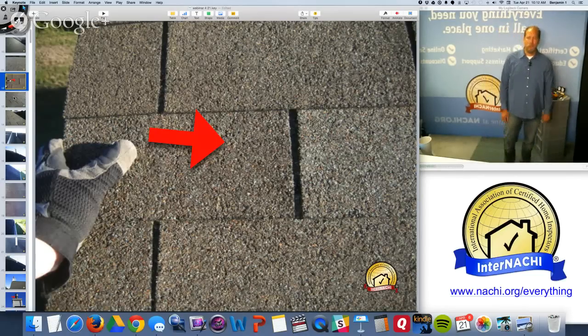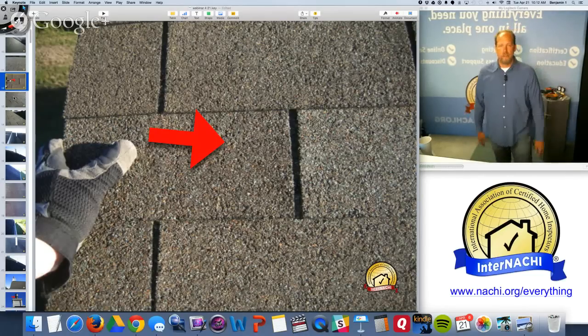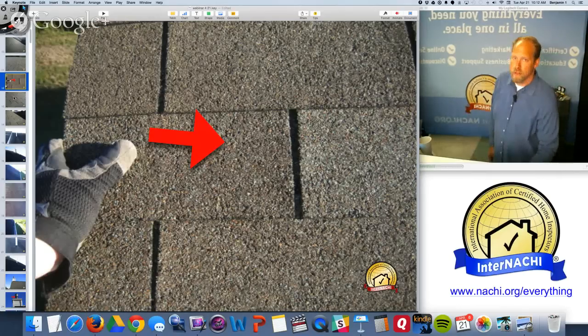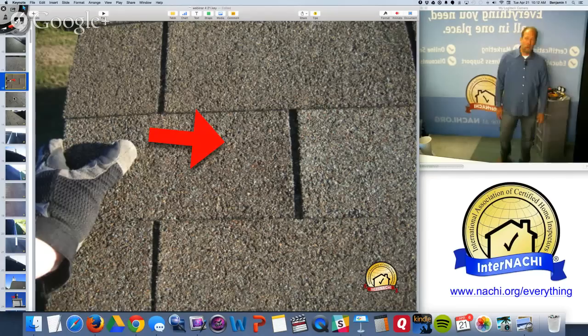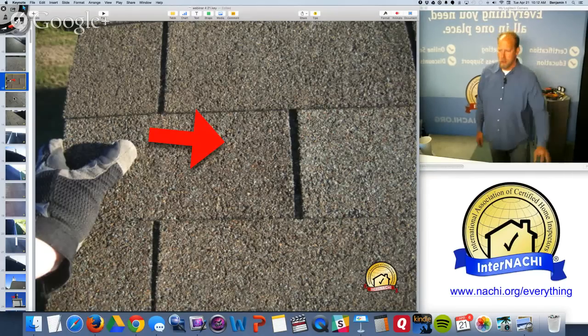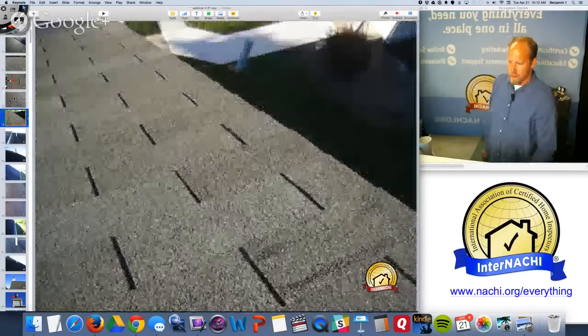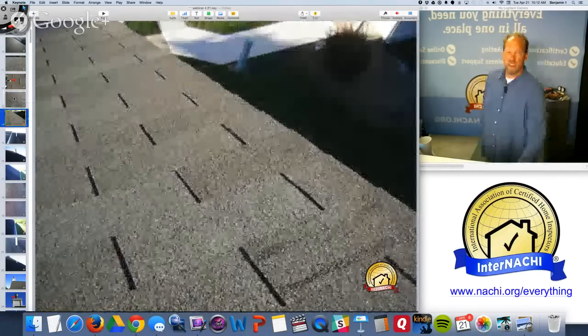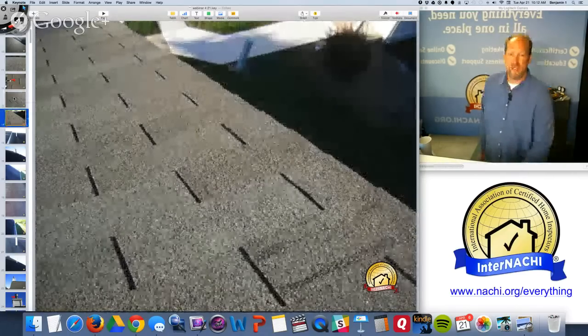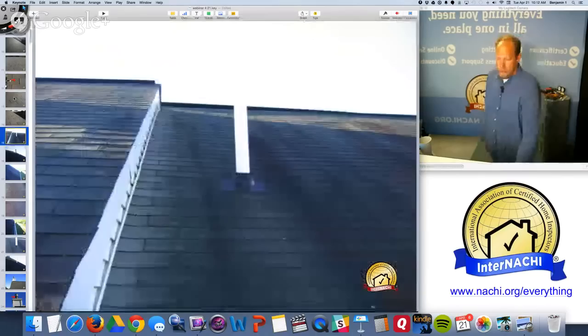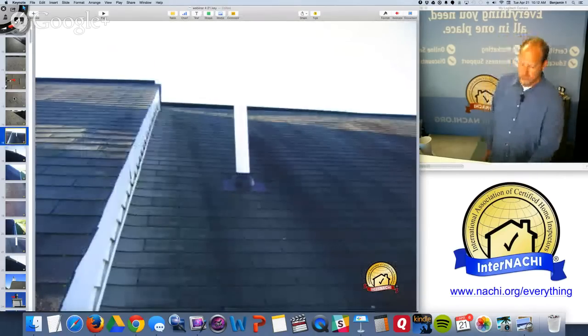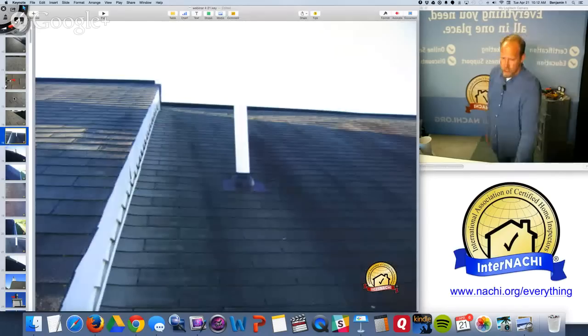This is a 15-year-old roof. It's approaching the end of its service life. It's probably a 20, 25-year shingle. So it's been beaten by some weather. This is a northern climate. The winters are harsh. The rains are hard. So I want to take a look at the condition of the material, looking for any missing parts, cracked shingles, blown off tabs. There's discoloration, no big deal. That's cosmetic. There's roof penetrations.